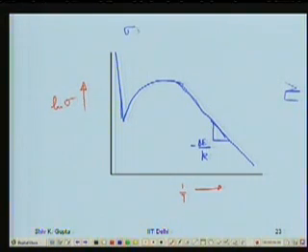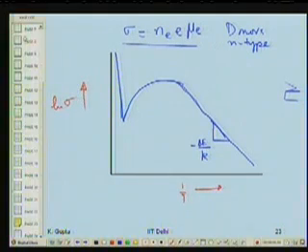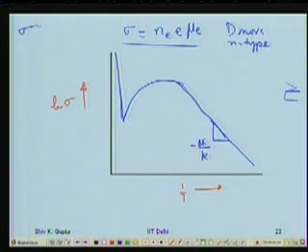Actually, I say sigma for N-type should be the number of electrons in the conduction band, n, times e times mu e. The second term will be negligible. Similarly, this is for the donors or N-type, and for the P-type the same thing would apply.